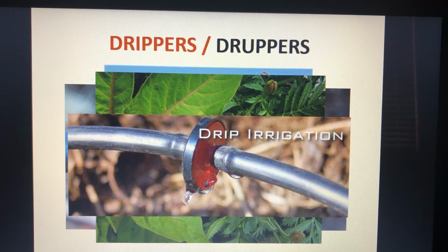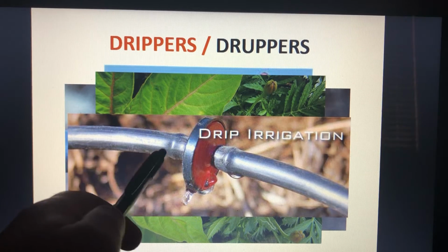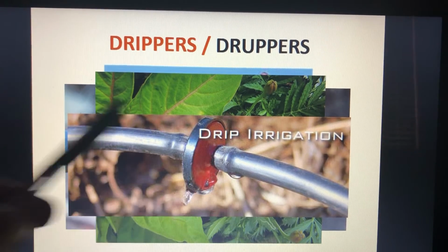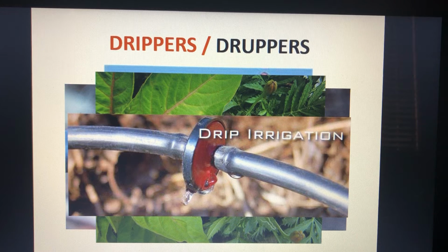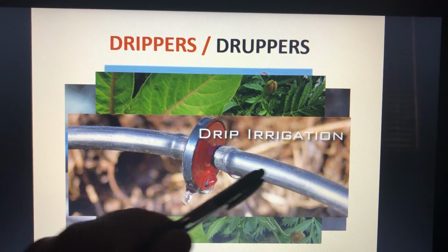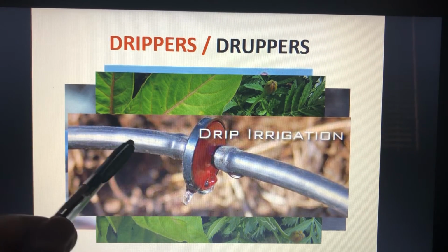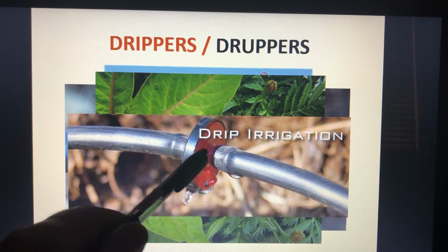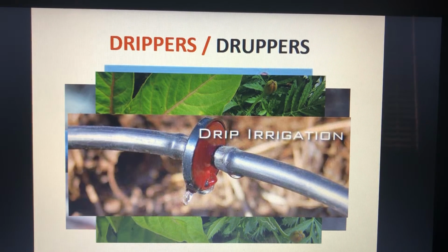Secondly, it's inline, as said earlier. So you've got this dripper with these 2 lines that are attached to your dripper. And it's very important when you're using this kind of dripper that there has to be a standard. So these lateral lines have to be a specific diameter, and you have to use a specific size when you are using this kind of dripper.